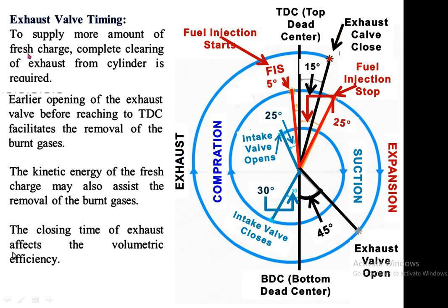To supply more amount of fresh charge, complete cleaning of exhaust gases from the cylinder is required. Means during the suction stroke, if we want to have sufficient fresh charge inside the cylinder, for that we have to completely clean the exhaust gases during the exhaust stroke. For that, generally during the exhaust stroke, the exhaust valve remains open till late. Earlier opening of the exhaust valve before reaching the top dead center facilitates the removal of burnt gases.